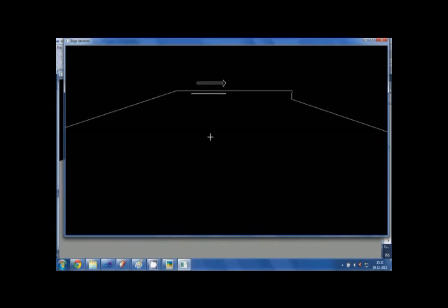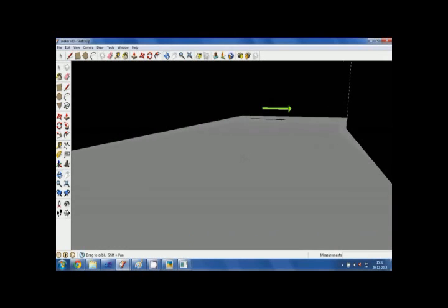So a good way of testing if you're at the middle of the lane or middle of the corridor or not is whether the sum of the slopes of the two lines is near about 0. And you'll find that if you can do your Hough transform properly and you add the slopes, you always try to keep moving to such a point that the sum of the slopes is 0. If at a particular angle, say at an angle like this, this line and this line, the sum of these slopes would not be 0, it would be non-zero.